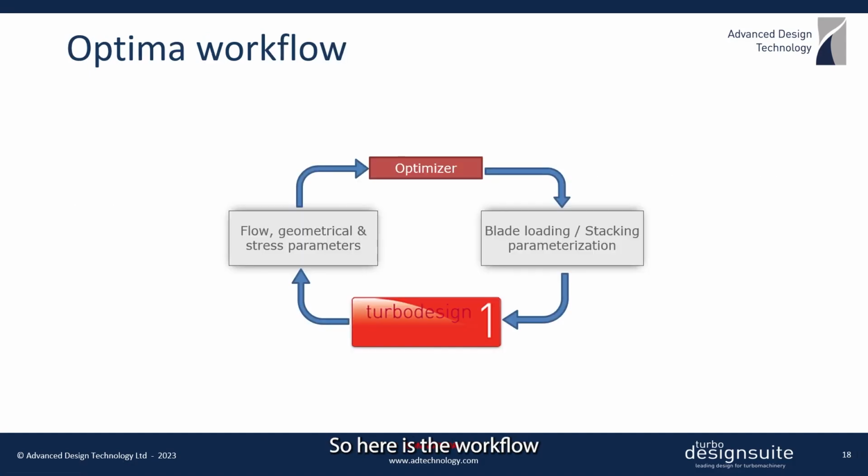So here is the workflow used by the optimization, where the blade loading and stacking parameters are used to generate the blade shape in TD1, and then the resulting performance parameters are fed into the optimizer, which basically applies MOGA to drive the solution towards the optimum design.